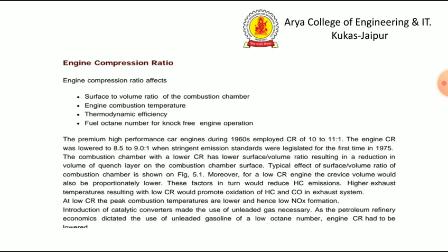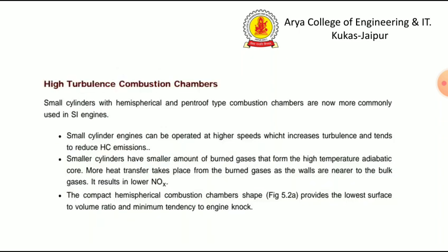With the use of unleaded gasoline of a low octane number, engine compression ratio had to be lowered. The principal disadvantage of lower compression ratio is that it has poor fuel efficiency, and it also results in higher carbon dioxide emissions.